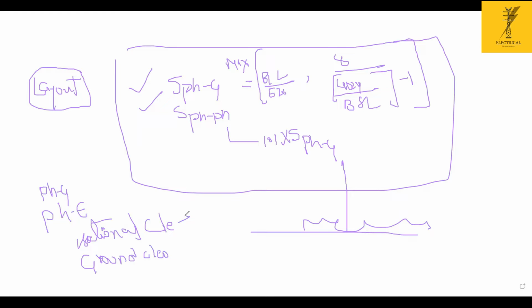What is a sectional clearance? A sectional clearance ensures a person can work on one section when the other section is in charged condition. Both depend on the phase to phase and phase to earth clearances, which are the fundamental things.